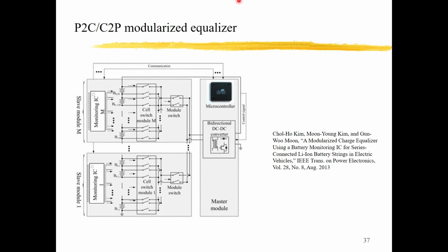200 volts. 200 volts means, if we think that one cell, because we use lithium-ion batteries, for each cell the voltage level is around 3.7 volts for one cell. For 200 volts, there are more than 50 cells series connected together, more than 50 cells.